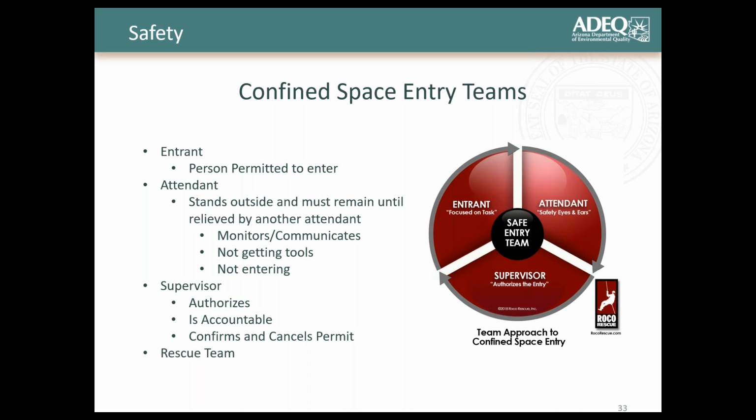Another portion of your confined space team that you may want to acknowledge is your confined space rescue team. Rescue team matters. You need to be ready to get out of that space at a moment's notice, and if you can't, you want to be able to. It's always nice to have a rescue team available to you. Now, a lot of folks like to use the fire department as their rescue team. And if that's the only means, communicating and letting folks know where you're at and what you do is probably an important part of your confined space entry program.